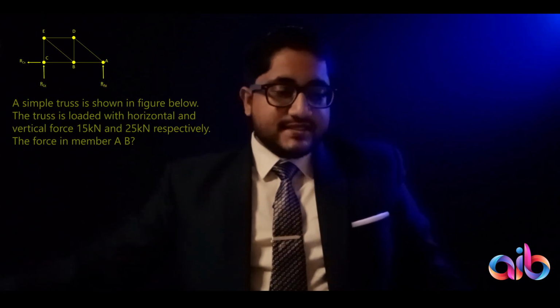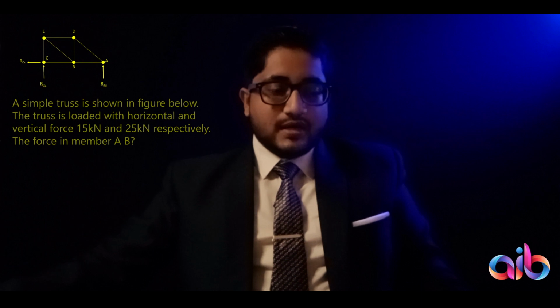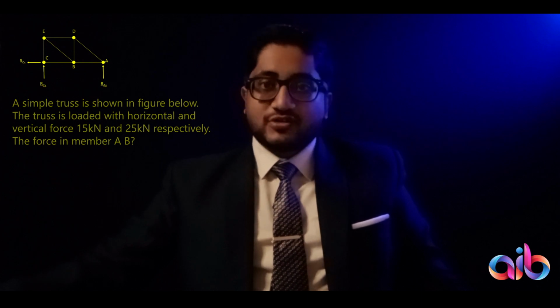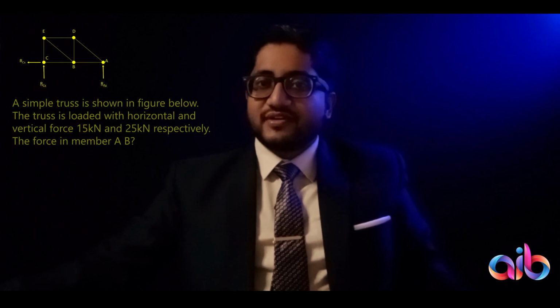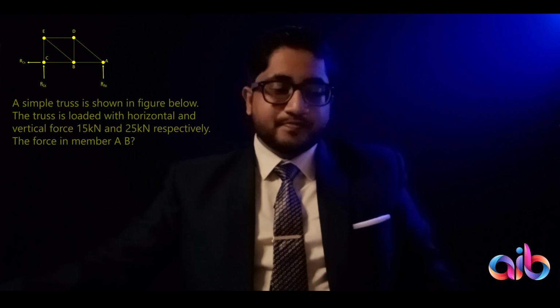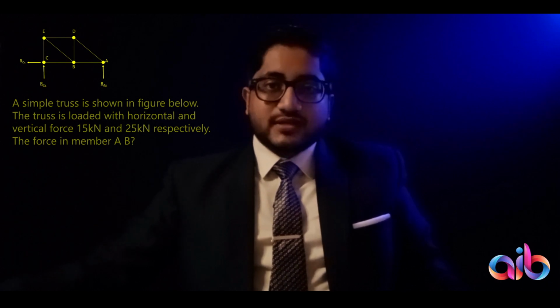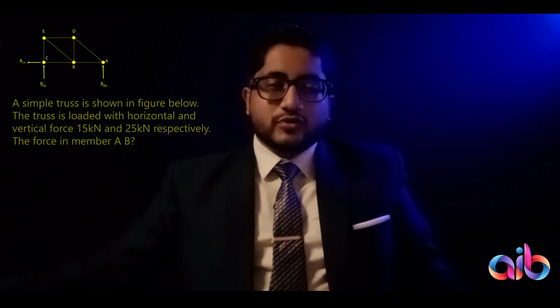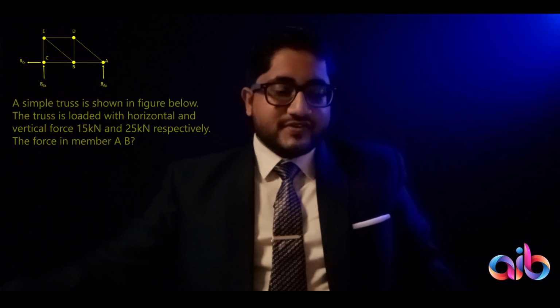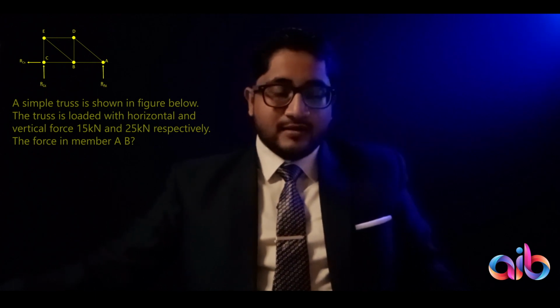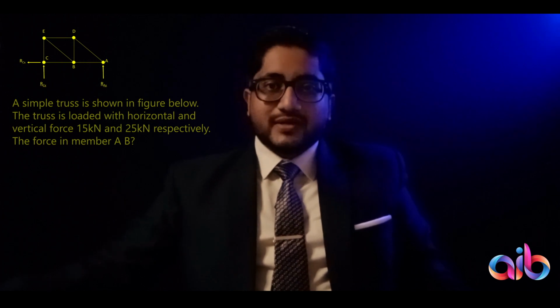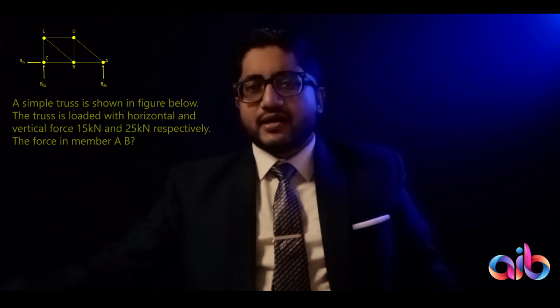So in this question we can see that there is an image of a truss which has been given to you, and the truss has two forces acting, one in the x direction, one in the y direction, of 15 kilonewton and 25 kilonewton respectively. And there are two supports, one is a roller joint and one is a hinged type of joint, and there are 7 members. And how many joints are there? 1 2 3 4 5 joints are there, each of length L. So obviously now we know what the diagonals are going to be, it's L root 2, because it's a square and diagonals are root 2.